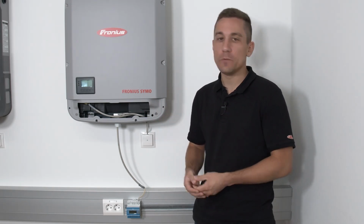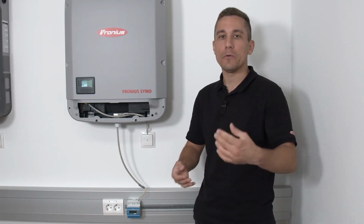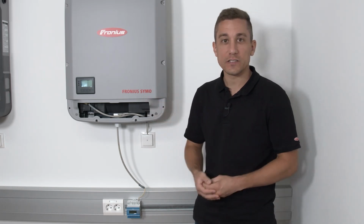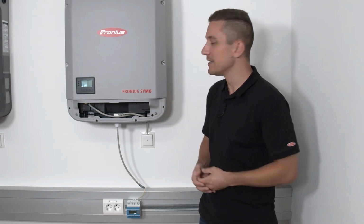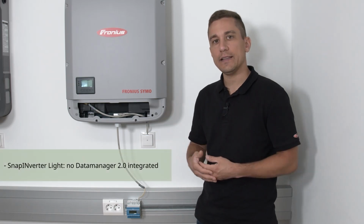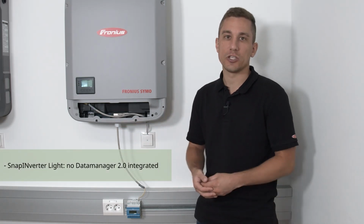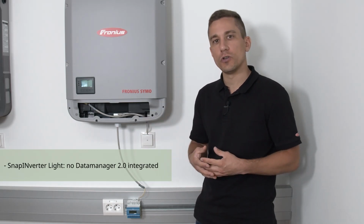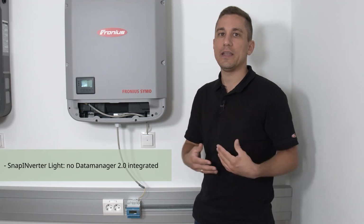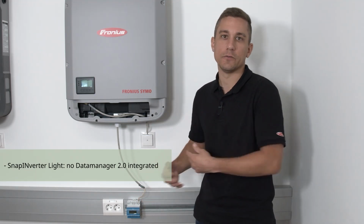In this case, we want to show you how to do a dynamic power reduction on our inverters without Data Manager 2.0. I mentioned it is a light device, so snap inverter light. And what does light mean? With the light devices, there is no Data Manager 2.0 card built into the device, and therefore we want to show you a possibility to do a dynamic power reduction on these devices together with an S0 meter.